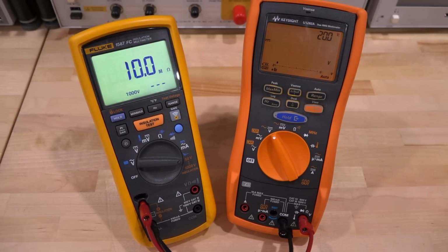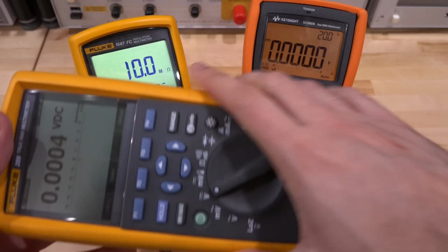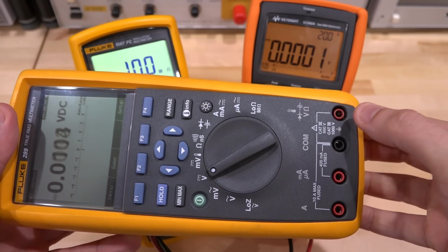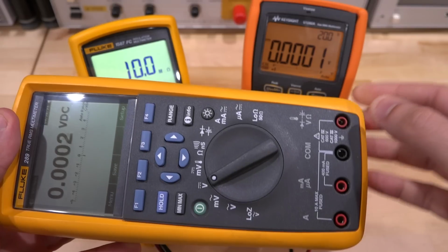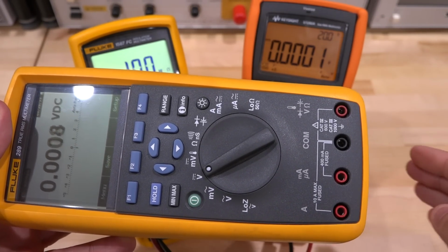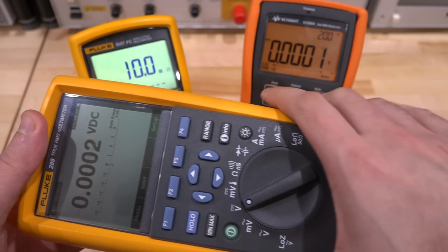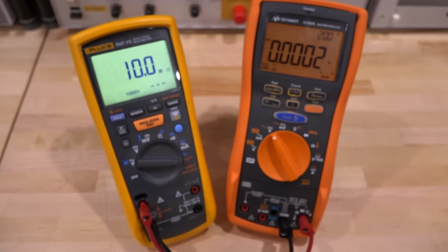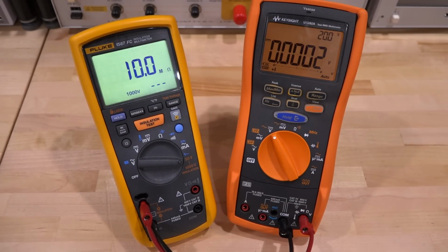What I suspect is going on is that the input protection of this is beginning to kick in because this is not really supposed to work above 1,000 volts. So the impedance begins to drop ever so slowly, and eventually at some point the input protection will kick in and probably shunt the input, or maybe a spark gap will shunt the input. So I think that leakage might be internal. Let me know what you think about that.